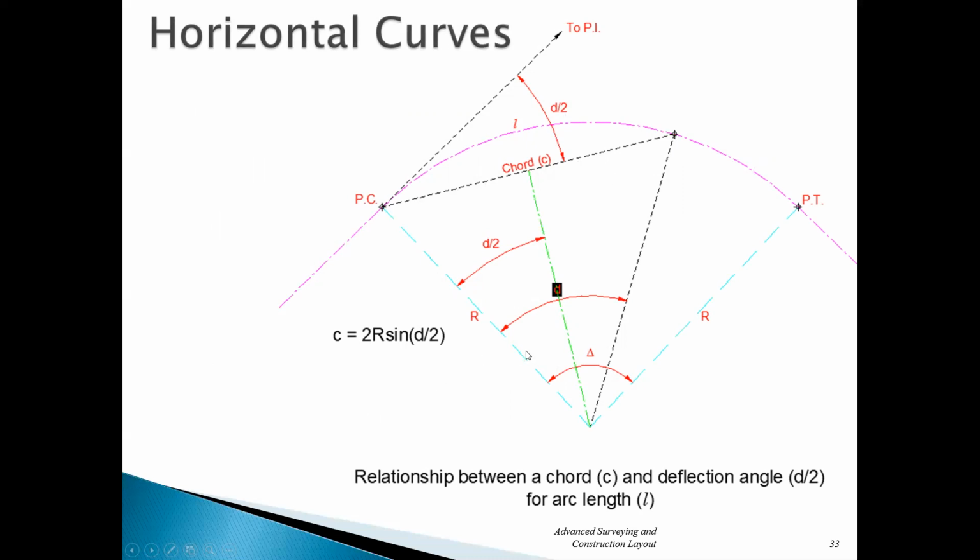And what this is showing you is this angle here to that point is actually angle D. It's twice that. And this angle up here is always half. So Jake, there's your geometric relationship. The angle at the center is always half over here. So if I go to the next station, I would have an angle here, and that one's going to be half. And you're using this equation, 2R times the sine of that deflection angle, to get this distance.